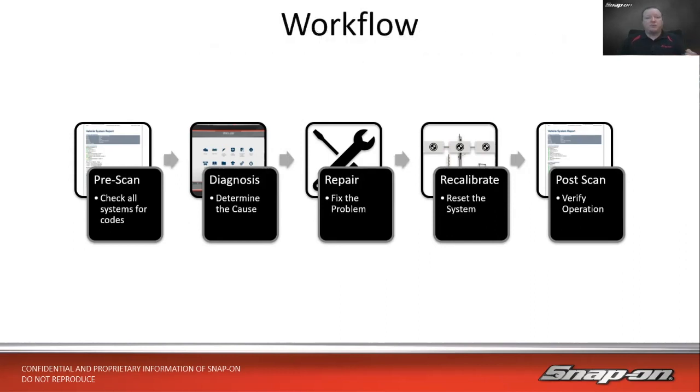So it's always good when we go through diagnosing a vehicle, or really any situation with a vehicle, to have a good workflow: start here, continue here, which gives us the steps to follow. A repeatable workflow is key, right? One that I can follow every time and do it the same way, so I'm not skipping any steps. So the first thing we would want to do is, we bring the customer in and we start writing them up. All right, what is the problem with the vehicle? What's the year, make, model of the vehicle? What's the customer complaint, etc.